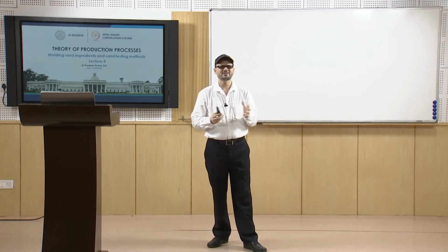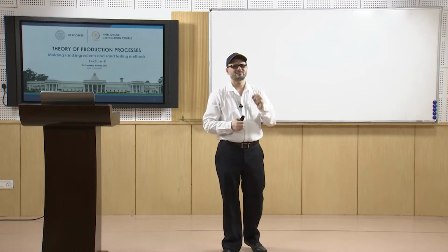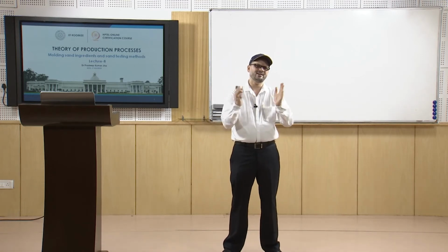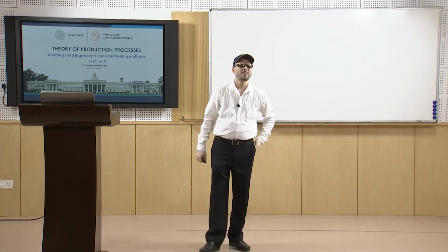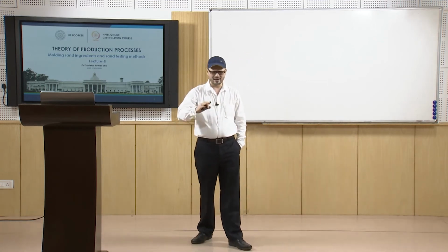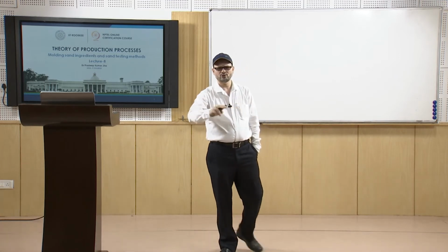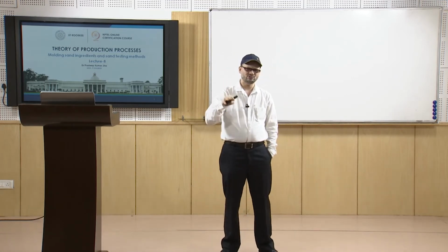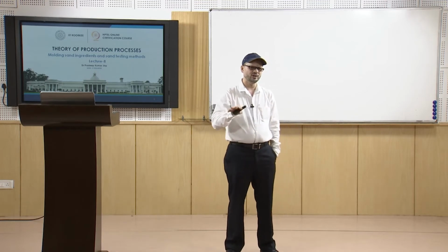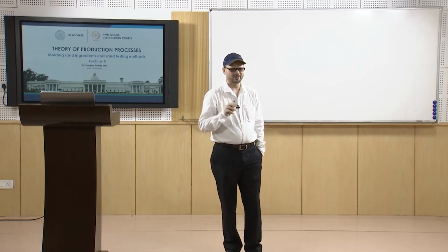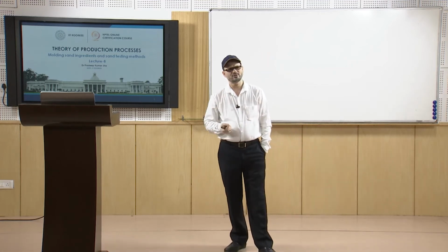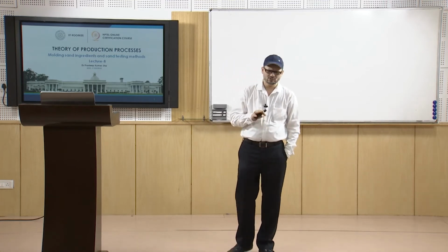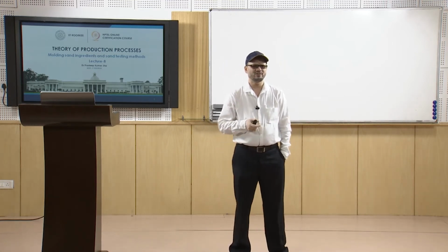Cohesiveness is the property where the sand grains have the tendency to bind to each other. Flowability means it flows like a fluid and goes into every corner easily. So, if it is more flowable, it will go easily into the cavity at different places. Suppose you have the sand and you are adding clay and water. If you increase the water, the flowability will be more, so it will go easily into the cavities.